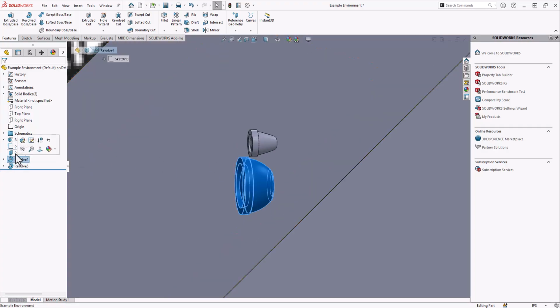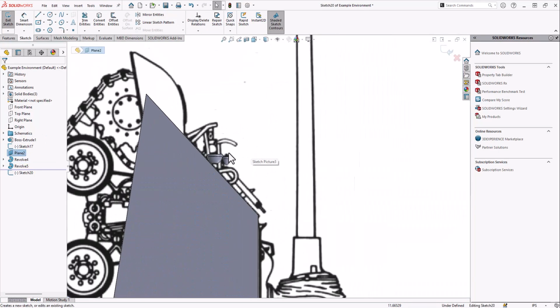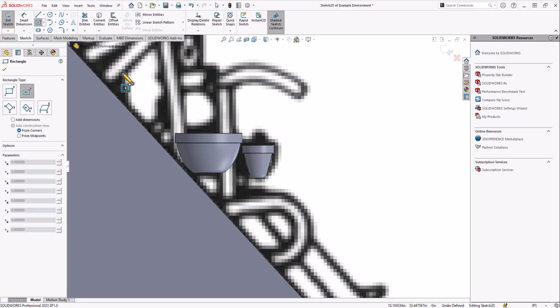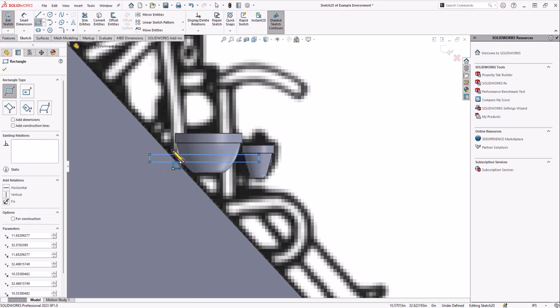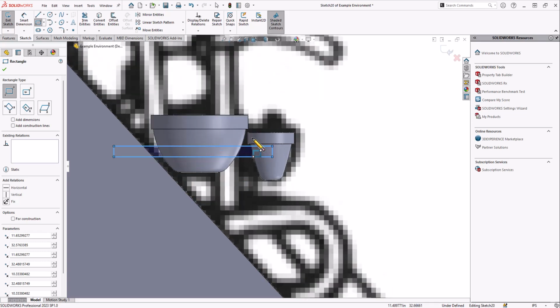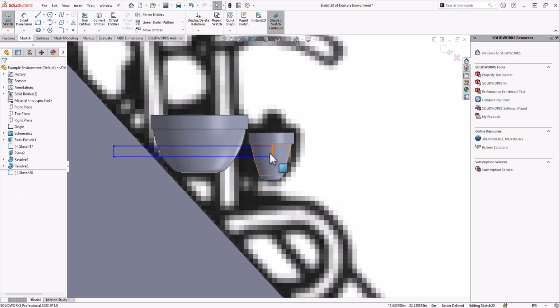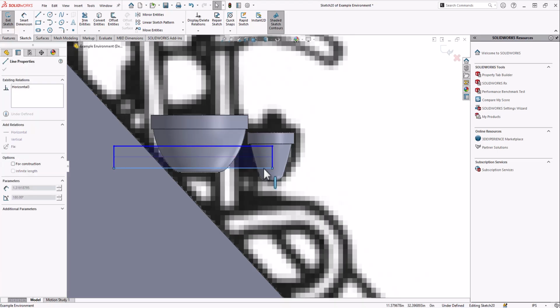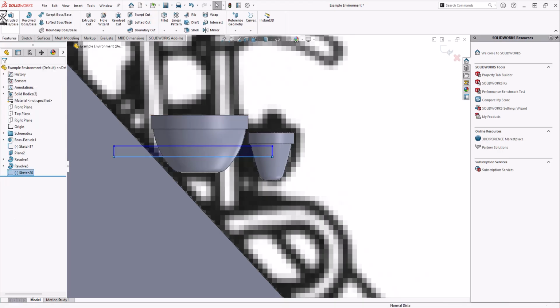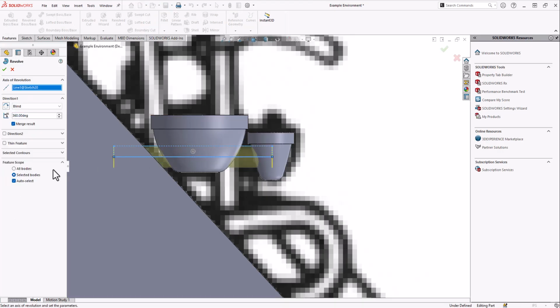Then what we're going to do is create the geometry that constrains it to the vehicle. I'm going to do that with just a rectangle that goes through, and the rectangle is going to be half the width that you want it to be because we're going to revolve it. So if it was this wide, it would revolve and be twice that thick. I just used my hands to show that on my screen, which is useless. But if I do it at half the diameter, so the radius, then when I revolve it, it'll have the proper diameter. So like that.